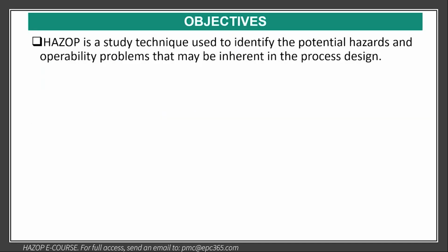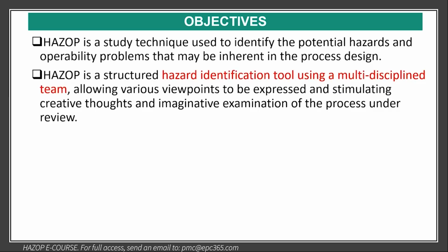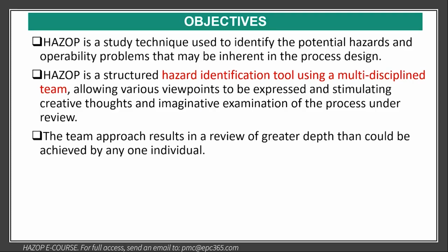HAZOP is a study technique used to identify potential hazards and operability problems that may be inherent in process design. HAZOP is a structured hazard identification tool using a multidisciplinary team. So this allows various viewpoints to be expressed, simultaneously creating thoughts and imagination examinations of the process under review. So the team approach results in a review of greater depth than can be achieved by any one individual.